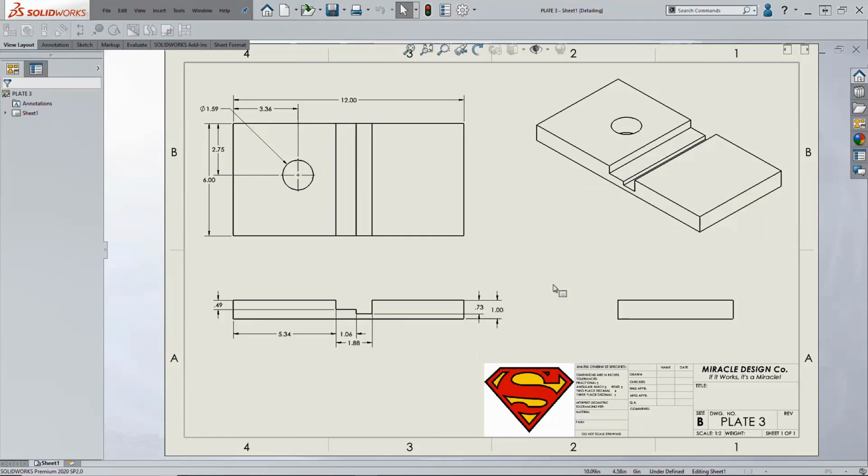And that's what detailing mode is. If you want to open this up just to print it, just to review it, it opens up lightning fast because, again, it's just the paper, okay? So a really nice addition for 2020, and one that everybody really needs to take advantage of, whether you're using large assembly models or not.